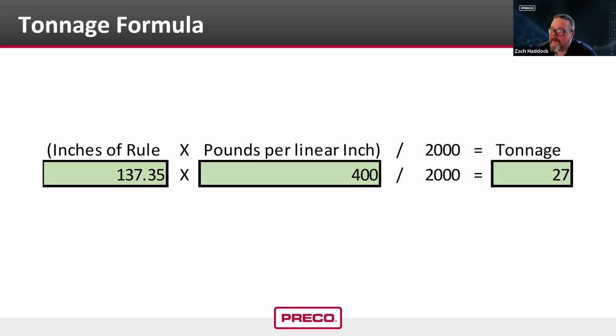If I'm on a 40-ton press, essentially I'm saving roughly a little over 10% of my, or I'm sorry, 20% of my cycle time just by running the minimum tonnage or the optimal tonnage. Now, there's a specific reason I put 400 pounds in there.